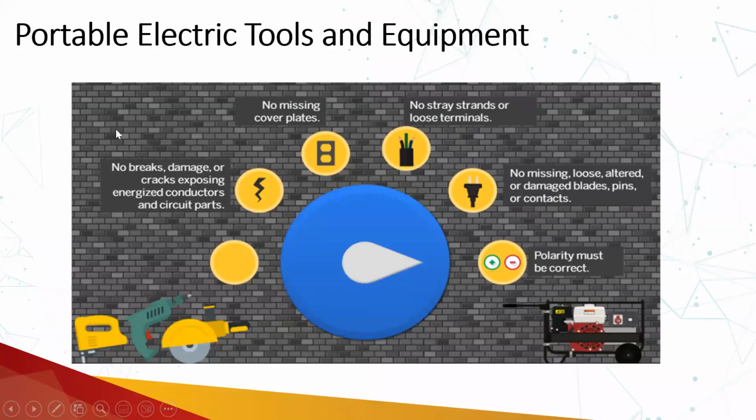And if we are using those portable electrical tools and equipment, we should ensure that we are using a GFCI with those.